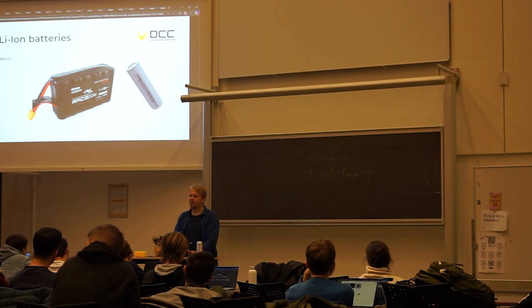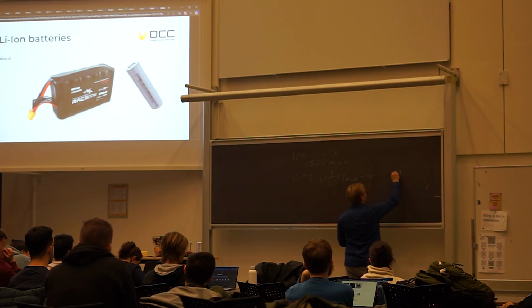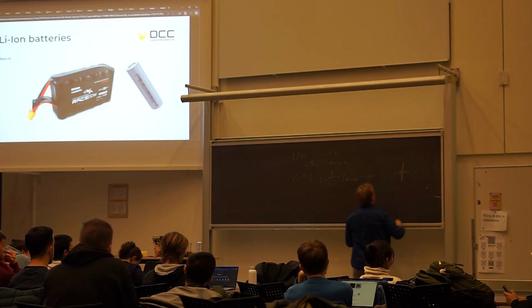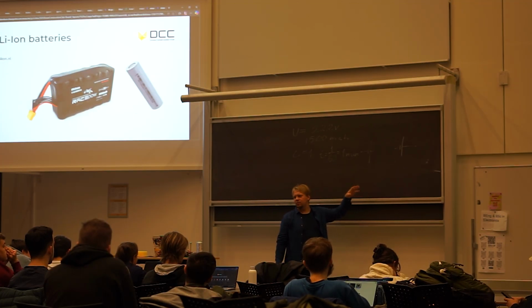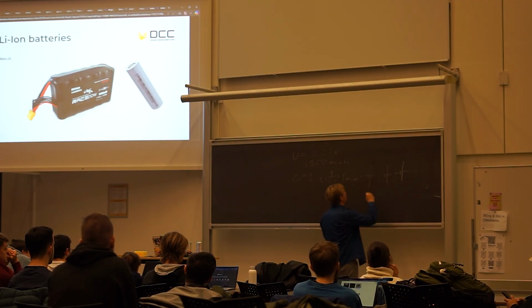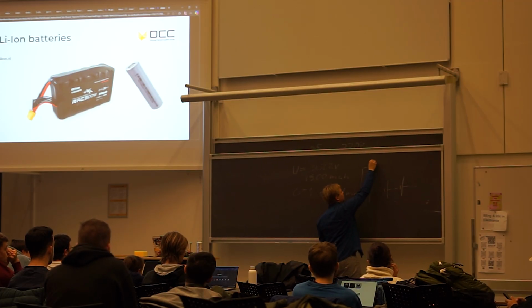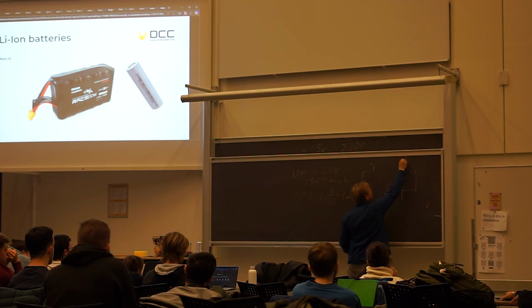Do they have a BMS internally or do we need one outside? Most of these things don't have any BMS. You use balance chargers, that's why you have this. So let's say you have a 3S battery. You have 2 big ports that you will use for power, big minus, big plus.